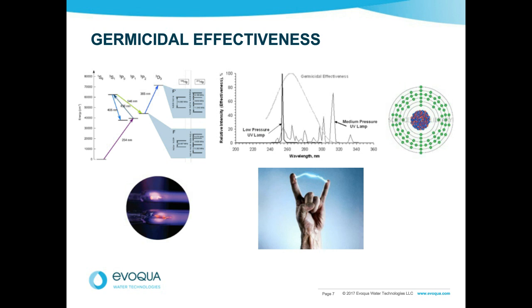We've developed and optimized an electrode, so we generate the active species in situ, and then we shed them off the electrode onto the UV lamps. So we have a non-chemical AOP. We piloted this, and it works very well. So yes, we have an AOP process, and we see it as a critical part of our product portfolio.